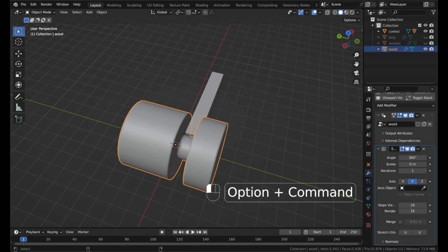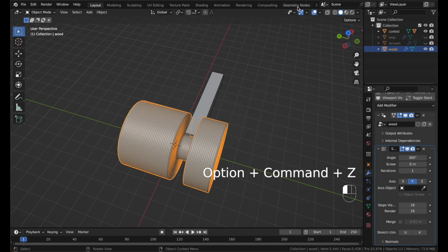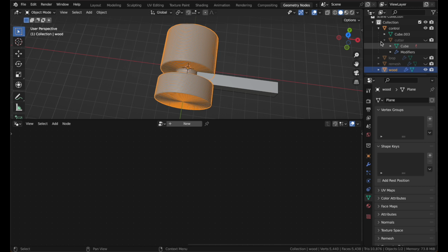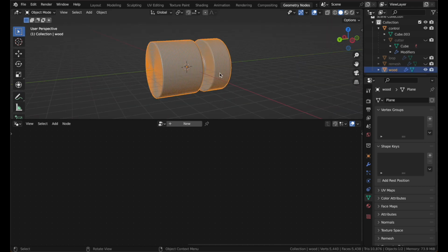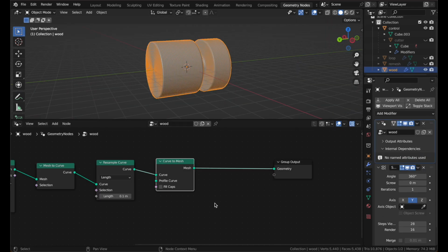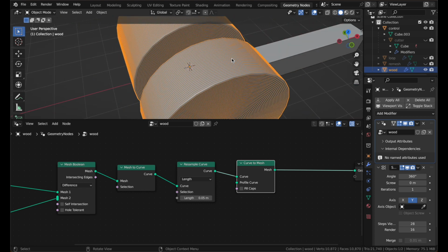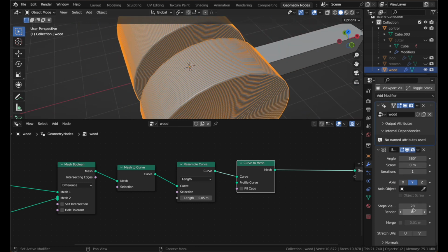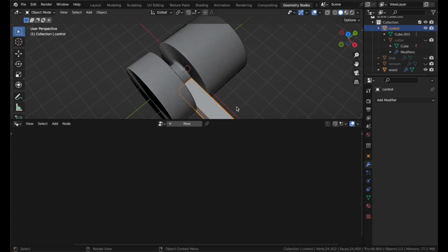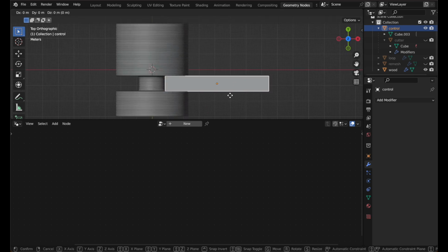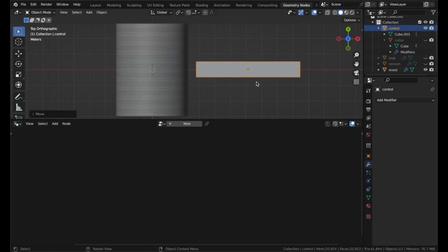If you'd like higher resolution in this direction, you can go back into your nodes and turn this to a smaller value like 0.05. Now it's an extremely dense mesh. I could turn this up more as well. There we go. That won't play in real time anymore, but it is extremely high resolution, which is nice if you're looking for something much nicer.